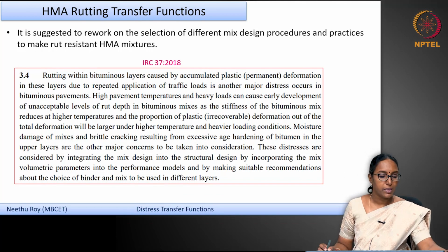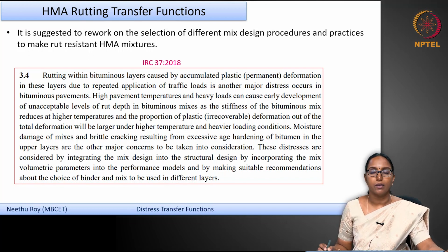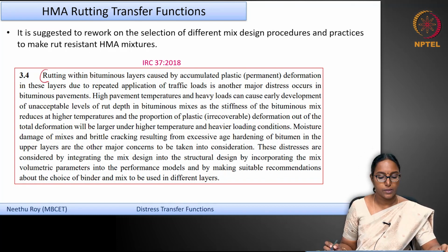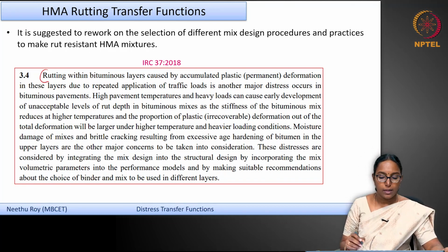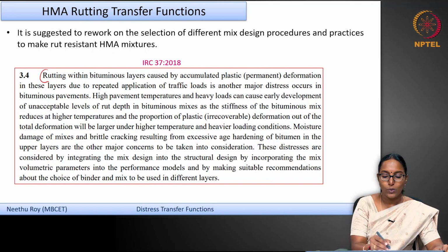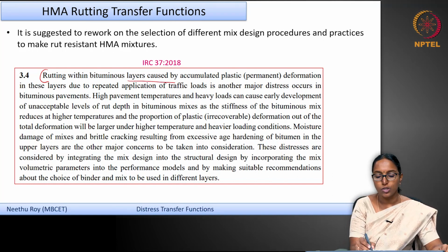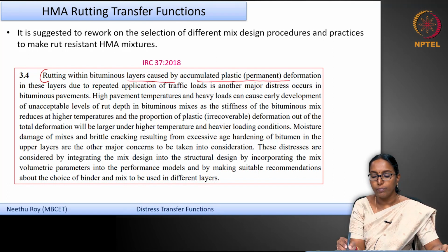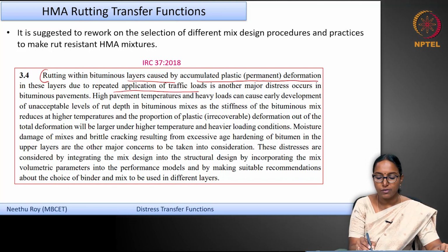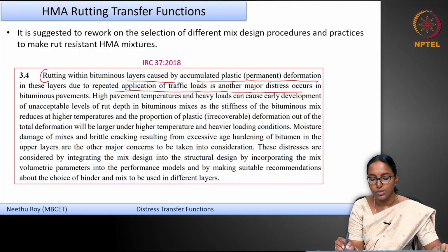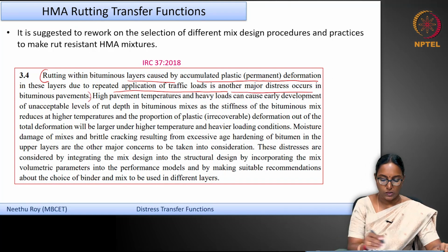Now, let me go back to the IRC design again. As I said, in the IRC method of design, you consider the subgrade rutting. You can read from here in IRC 37, rutting within bituminous layers caused by accumulated plastic or permanent deformation in these layers due to repeated application of traffic load is another major distress that occurs in the bituminous pavements.